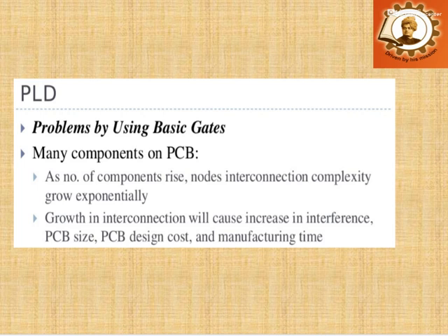If we are using some discrete gates and making a circuit by internal connections, it will take a larger space on your PCB, and your interconnections may interfere with other components. The PCB design will be higher cost and manufacturing time will be high if you are considering a bigger circuit. So to remove these shortcomings you can use a programmable logic device.